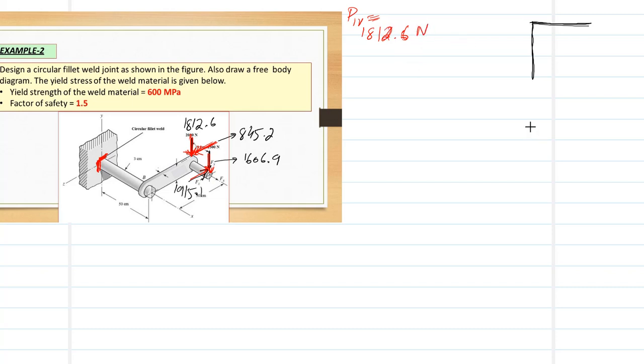This has three kinds of stresses. One is bending, acting downward on the centroid. This is sigma B1V. Then we have direct shear, again acting downward, which is tau D1V. And then we have a torsional shear stress, because it's a non-symmetric weld, concentrated only at the free ends, and we know the distances.